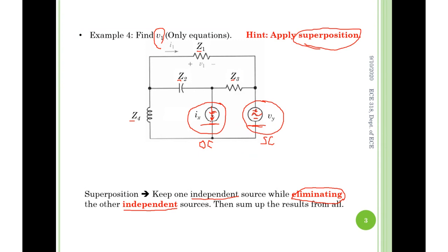Kevin is basically right. So what's the correct answer? Actually, make it easier. The voltage across an open circuit is what? Unknown. Okay. Absolutely not necessarily 0. It's unknown. It all depends on the rest of the circuit. Does it make sense?